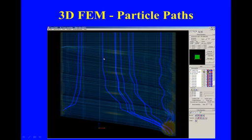Now, the really cool thing about finite element analysis and path lines is that you can do something that you can't really do in reality. In reality, we could set up a rig and inject some material here and watch it flow through the system. But in finite elements, we can do the reverse analysis. We can actually put a particle here and say, where does it end up? So if I click there, this particle would come from here. So from this point here, where does it come from?